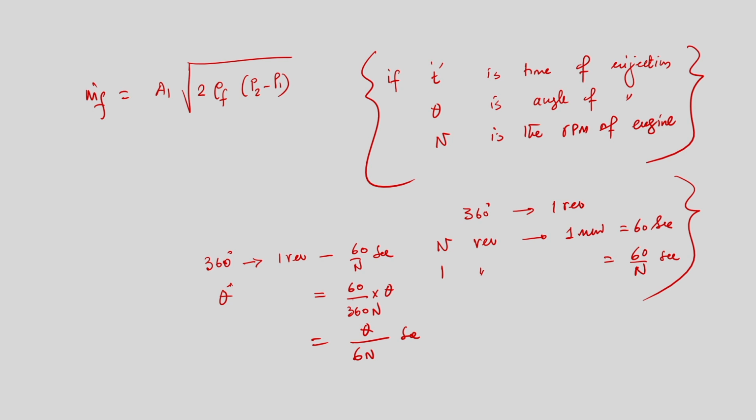We will do a little bit more mathematical exercise to see the kg of fuel which is supplied per cycle, which is nothing but proportional to 1 by RPM, and from this we will see why diesel engines are more suitable to run electrical generators, why diesel engines are preferred.